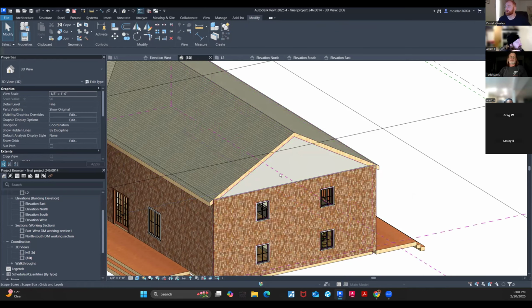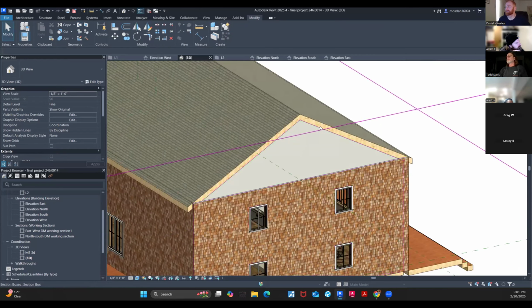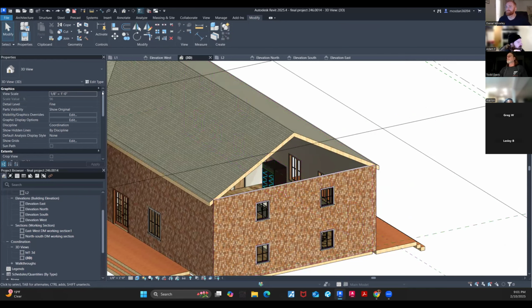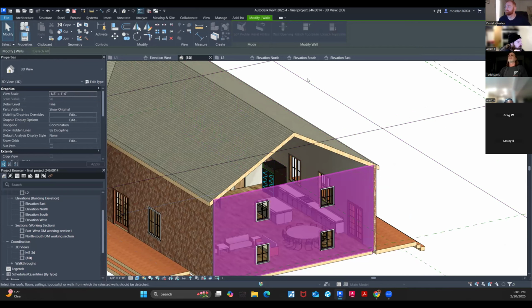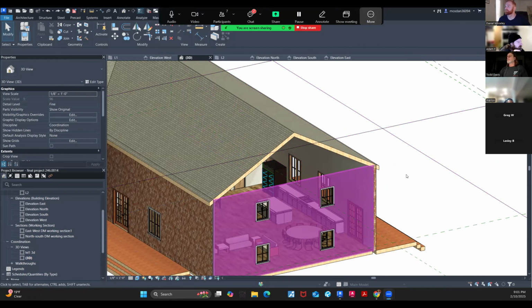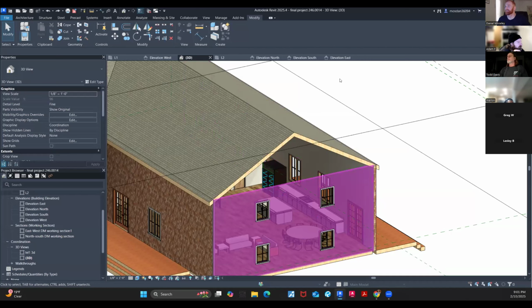Okay. So, now it looks like it has a different material type there. I'm not sure what happened there. Yeah, it's like generic. Let's hit Control Z. So I want you to click that wall and detach it first. So do the one to the right. Now hit escape twice, and then click it again and then attach it. Sometimes it's holding on to old stuff, and it tries to do its best, but it fails. So hit escape. Yeah, there you go.